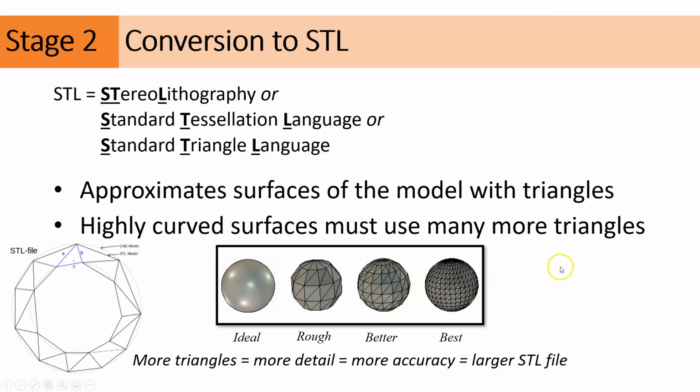Highly curved surfaces must use many more triangles, all right? So when you have a lot of curves in your model, you'll notice that your STL file, your model file, is going to be larger than if you're printing a cube. All right, so let's get a little more into the nitty-gritty details of the STL file.